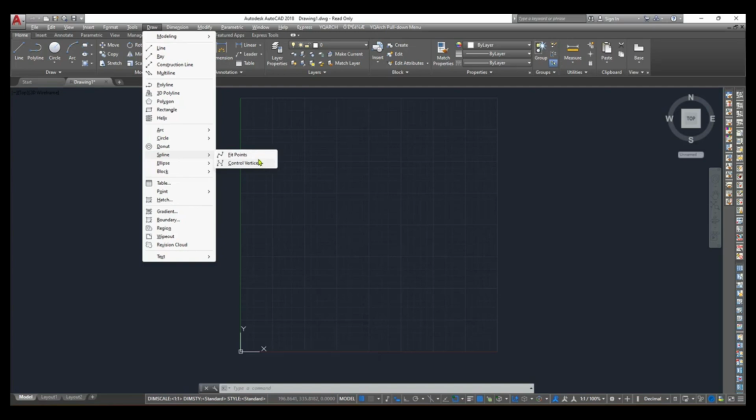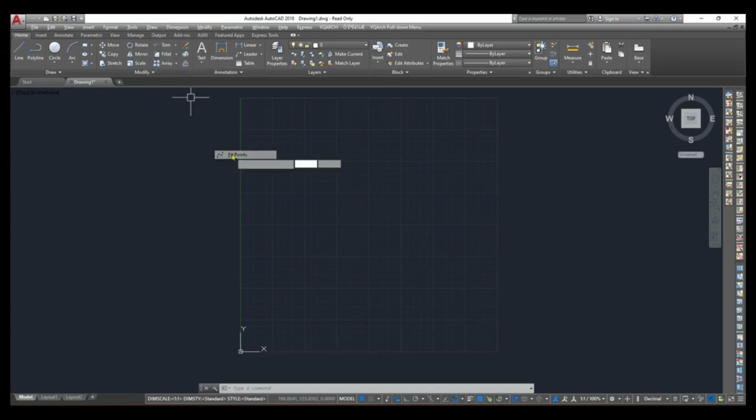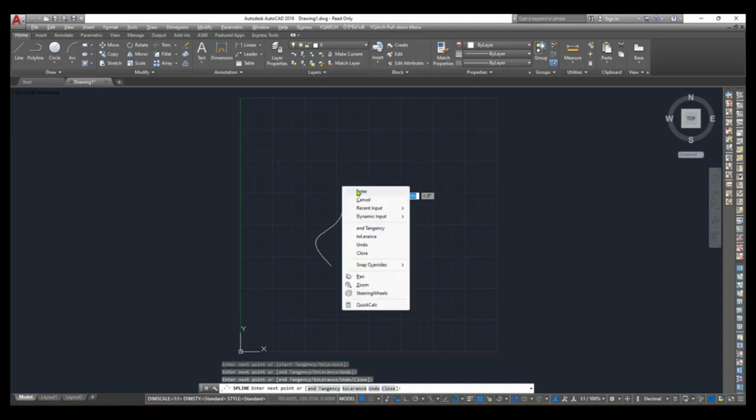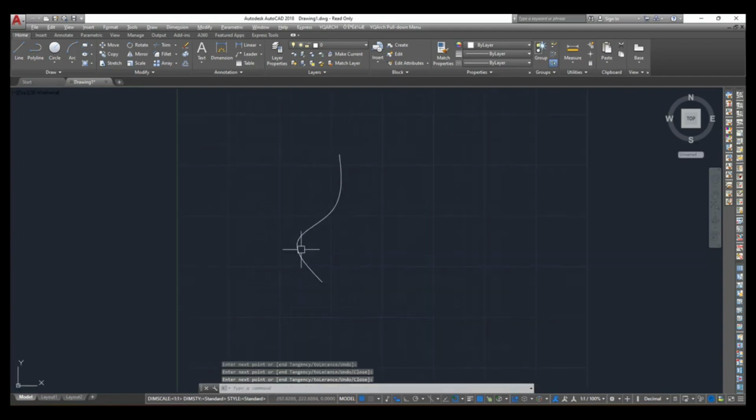So both are a little bit the same. Just select the fit point option, make sure your effect is off to get extra smoothness while making the design. Spline we use to design in furniture, or else you can do any interior type or freehand drawing. So let's work out with this. I just want to draw this first point and then move however I want, second point, third point, like this. Now I have a shape like this.